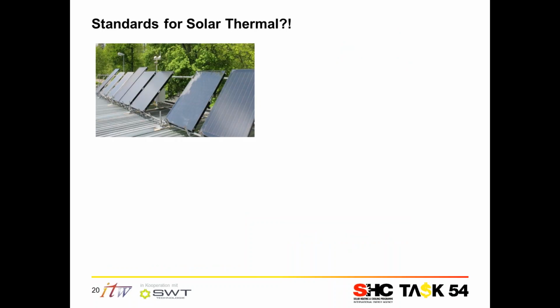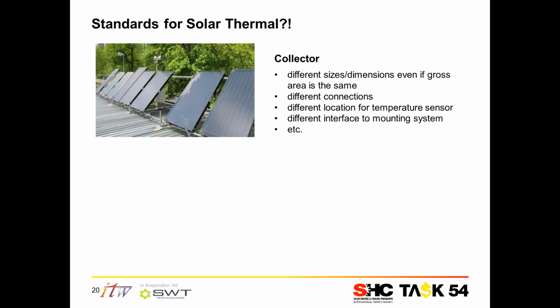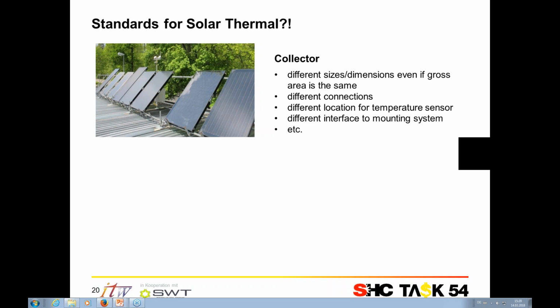So what about standards for solar thermal? If you take a look at the collector, it's not really standardized so far. We have different sizes and dimensions, even if the gross area is the same. We have different connections for inlet and outlet and for connecting it to the solar loop. There are different locations of the temperature sensors, and there are different interfaces from the collector to the mounting system, which adds difficulties to the installation process.